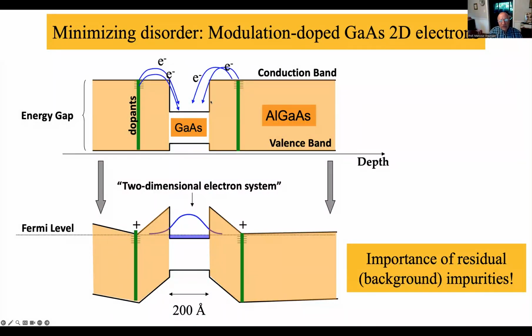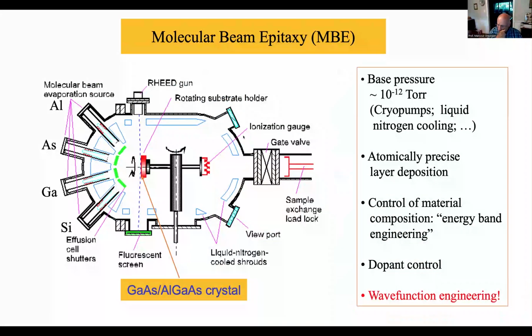And what that means is you could put these dopants far away and also make sure that the material that you grow is very pure. So it turns out the big breakthrough that we have made past couple of years is essentially making this material extremely pure as we grow it with molecular beam epitaxy to reduce the residual impurities.